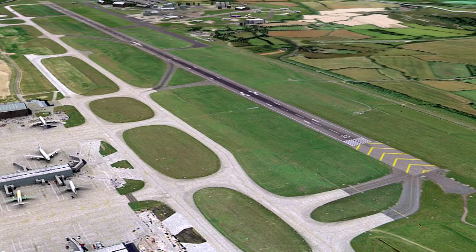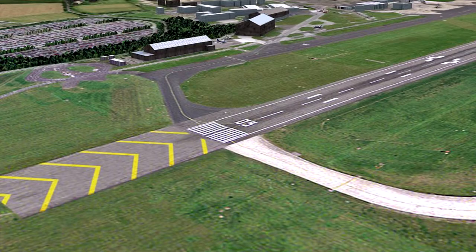Even if a pilot is taking off from the other direction, he cannot use the stopway as an extra length at the end of the takeoff run. Even when landing, the pilot must not use the stopway, either to land onto or use to come to a stop. To help the pilot recognize the stopway, it should be distinctly marked, as shown here.